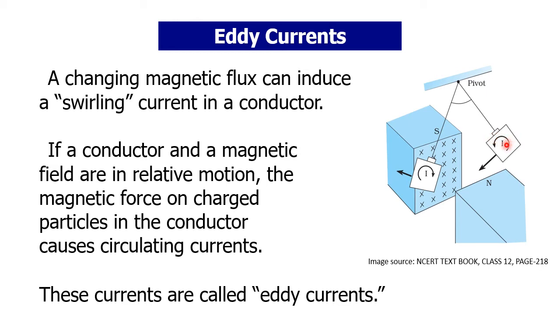Whenever it is coming into the magnetic field, flux is increasing, so it has to stop. In that manner, flux is generated in the anti-clockwise direction. Whenever it is going out of the magnetic field, flux is decreasing. It doesn't like the decrease in flux, so current will generate in the clockwise direction. That you can analyze according to Lenz's law. Eddy current is also like an induced current, so it opposes the original cause. So by applying Lenz's law, you can get the direction of electron rotation.